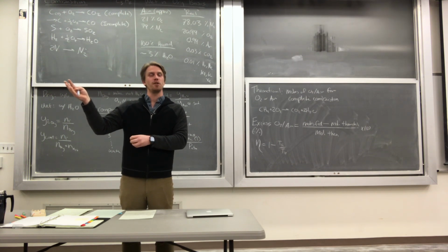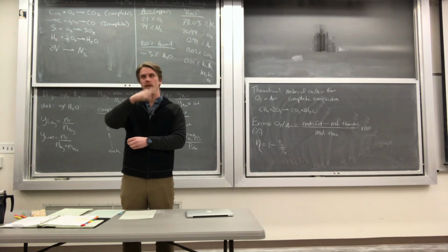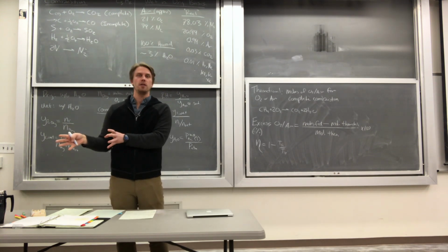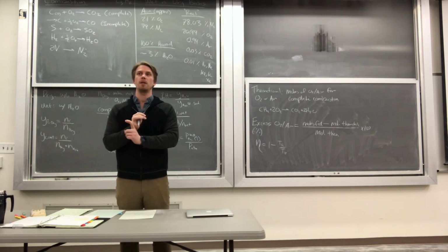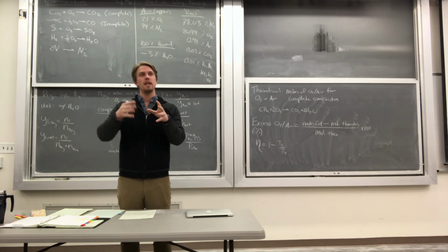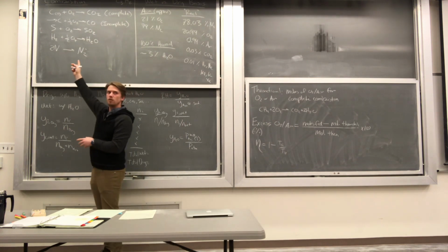Chemical looping combustion. The idea is we extract oxygen from the air in some sort of solid phase reaction with the oxygen. Then we release the oxygen next to the fuel, and you burn the fuel in pure oxygen. That allows you to get to a higher flame temperature and increased efficiency, and the big advantage is that your product stream doesn't have any of this nasty nitrogen in it.